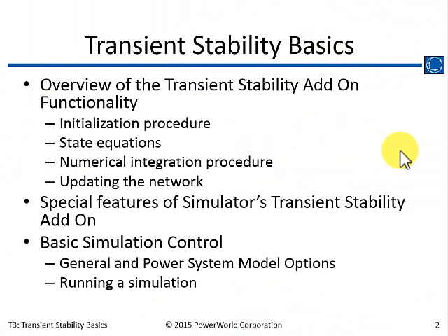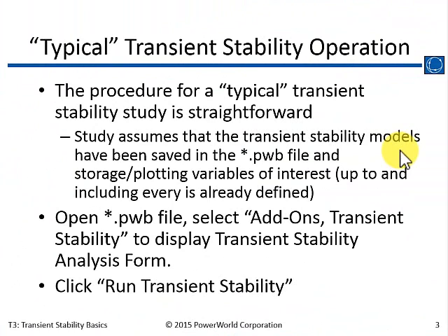We're going to start working with little cases and go through the basics of simulation with this small case. As I talked about, the basics of doing a run are really straightforward, particularly if you're using a PWB file. The PWB file will store everything associated with a particular run, all the options, what you want to save, store. We'll talk about plotting definitions. So if you've got a case, you can open it up and run it. And that's what we're going to do right now.